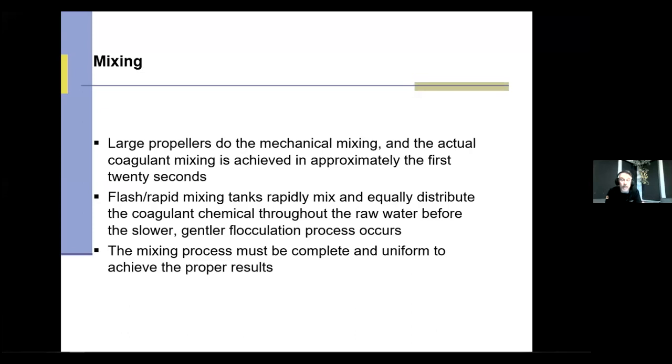Now, Shannon, you had a question about would chlorine gas be a good pH reducer? It can be, but we got to be careful, because if we're going to add it before our process, the water has a lot of organics in it. So if you're adding a little bit too much chlorine, you could create those byproducts before you even remove the organics. Chlorine gas does reduce pH, but I would rather use an acid or something that wouldn't create a byproduct first. So we always got to be careful about using a chlorine gas up front.